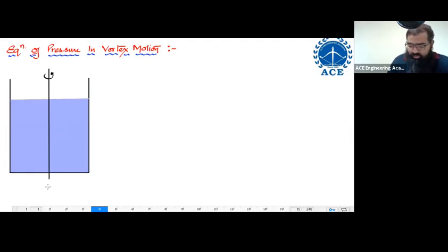So there are two axes over here important for me. One axis over here is z-axis. The other axis over here is radial axis. Two axes are important. Pressure should vary with respect to r as well as with respect to z. Pressure is supposed to vary with respect to both r and z. That means if I take a fluid element somewhere over here, there is some fluid element, let us say, I have considered. This fluid element, let us say, is at some distance r.